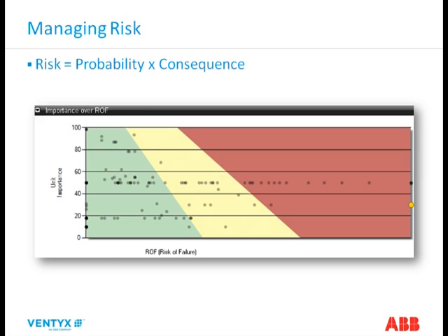A cornfield distribution substation transformer is not nearly as important as a generation step-up unit that's basically handling the output of a nuclear power plant. So that criticality and that unit importance is what we think is a very important dimension. So we look at both factors when looking at total risk of failure and in how O&M money should be directed towards making sure that as many of the units are in the green as possible, and then making investment decisions and life cycle management decisions on the units that persist in the red.